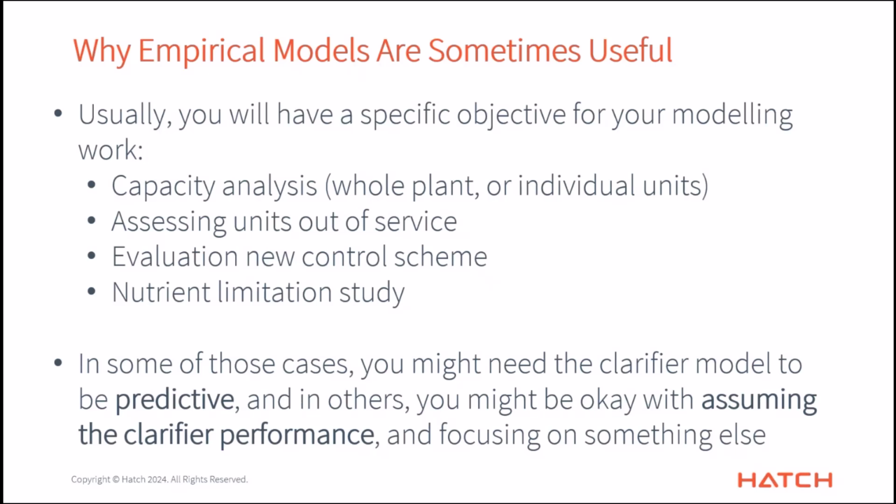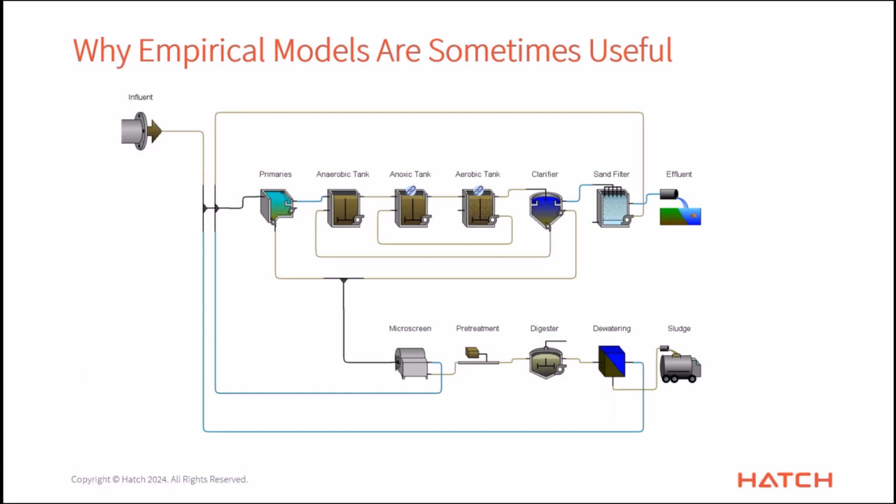You need to say, when it's loaded up a lot, I need to show that it's not going to remove as high a percentage of solids as it would under low loading, right? But a lot of the other time, if I'm really looking at the aeration capacity analysis, or I'm trying to study potentially the sophistication of my internal mixed liquor recycle or how alkalinity is affecting my nitrification, that's not really a function of what's going on in the clarifier for the most part. I might be fine with assuming that my clarifier is going to work okay. So therefore, I can pick one of the simpler models, just set it and go, and then really focus my time and effort on the biological part.